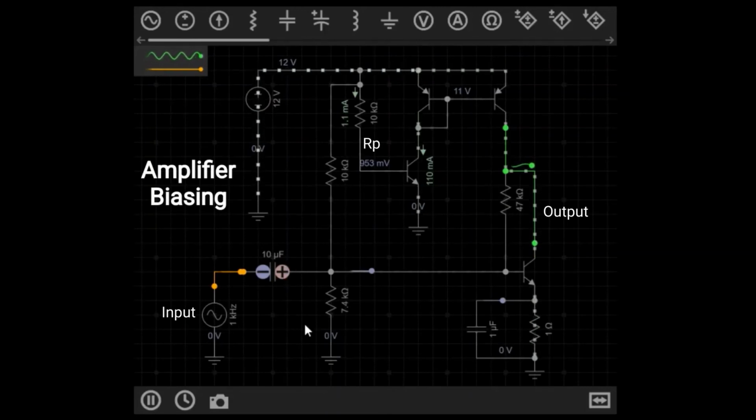You'll have some biasing resistors here that depend on your design, of course. This resistor provides negative feedback because without it, the voltage gain would otherwise be so high that you would end up with a square wave output from simply a 1 millivolt peak-to-peak input signal.